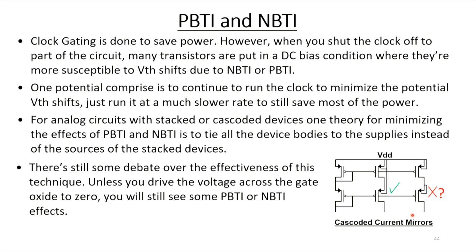Now, for analog circuits with stacked or cascoded devices, one theory for minimizing the effects of PBTI or NBTI is to tie all the device bodies to supplies instead of the sources of the stacked devices. And you can see here we have a cascode current mirror. The one on the left here has its body tied to a supply as opposed to tied to the source. Now, I think there's still some debate over the effectiveness of this technique. And, in my opinion, unless you drive the voltage across the gate oxide to zero, you're still going to see either some PBTI or some NBTI effects.